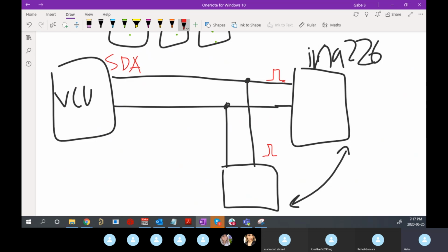But now let's say my current sensor is sending a high, and then another high, and another high, and 3 highs, right? Remember, because it's open drain, for it to send a high, it's basically let go of the bus. So it's relying on the pull-up resistor to do that high for it, right? Now my rogue sensor, I'm not sending a high, I have different data to send. I'm sending lows in all these cases. So I've now asserted the bus, I've connected it to ground.